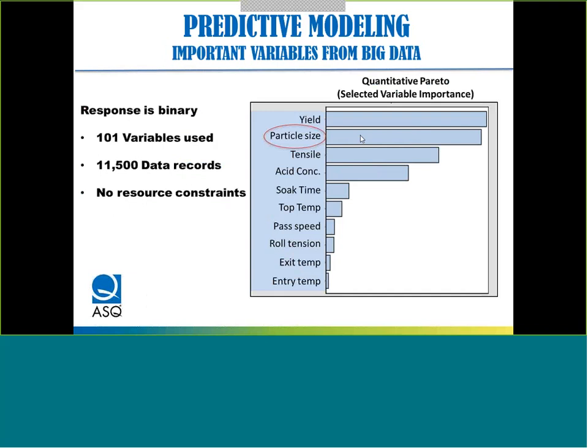And that conditioning of the surface of the metal is what is key to having the coating stick. So if that particle size starts getting larger and larger through time, it changes the surface tension on the metal and changes its ability to hold that coating. So by looking at the data end to end, we found the key variable, or as my academic friends say, it's one of those lurking variables that you don't know about.